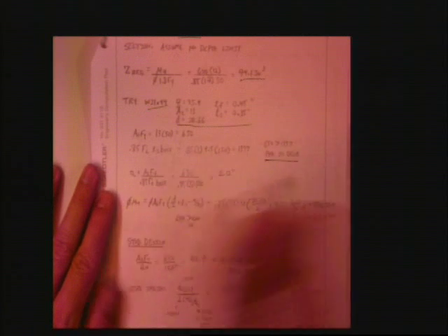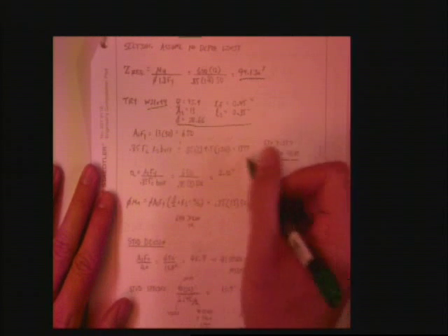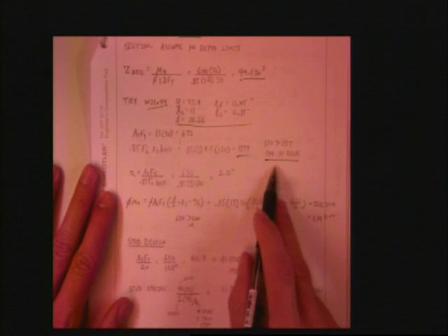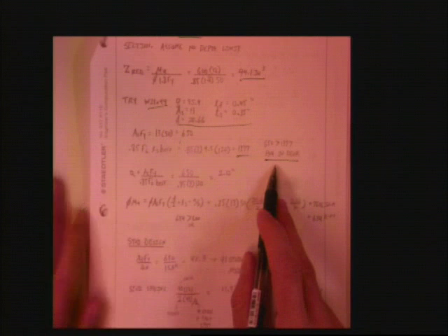Okay, so we're just looking at plastic moment. We get all this information from the steel manual. Take my A_s F_y. I still have my plastic neutral axis. I do my same calculation and I get 1377. My plastic neutral axis is still in the deck, so that was a good assumption.